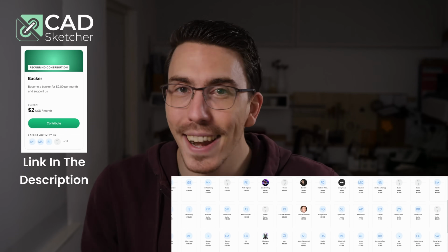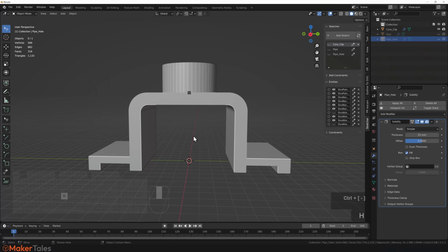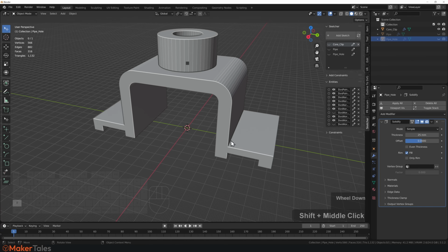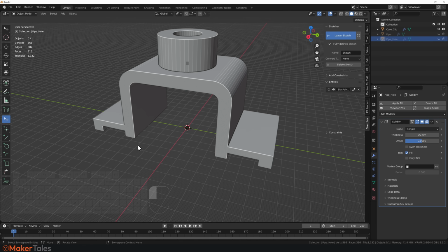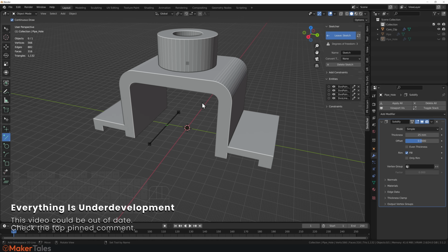Okay, with that said, let's dive straight back into that sketch. So let's first do those two little holes, and then we'll deal with a profile cut. So we'll add a new sketch. We're going to go from the top down. Now, unfortunately, this is a brand new sketch from a brand new work plane, so we can't reference off anything. So we need to create ourselves a reference line that's going to let us know how long this is widthwise.